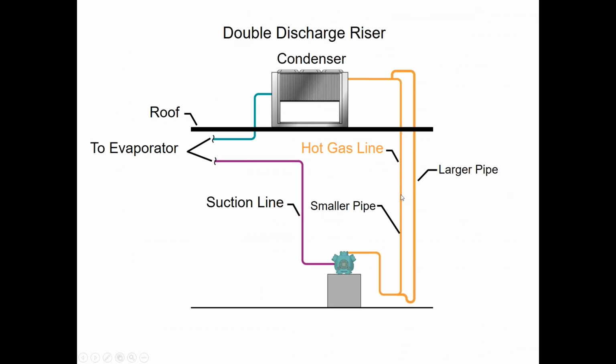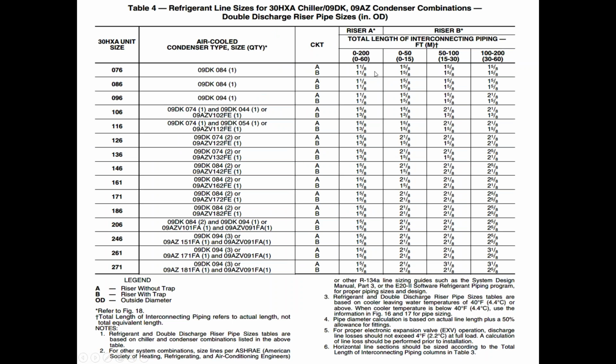A pipe is basically your speed riser pipe when the trap is full of oil because you're at minimum load. At minimum load we're not returning oil properly, or not pushing oil, I should say, properly. So we fill the trap up, and now our velocity picks up in the A pipe, and boom, now we're entraining oil back up to the condenser, out to the evaporator, and then back to the compressor. Okay. So that's how this chart reads.